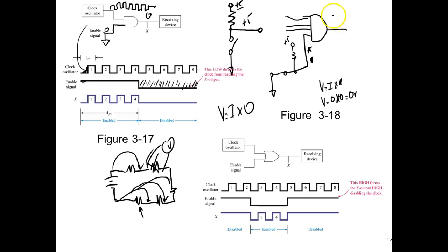It'd be a 0. That's exactly right. Well, what about those other inputs? They don't mean anything. I don't even care if they're highs. I don't even care if they're lows, right? You understand? As soon as you find a 0 on one input of an AND gate, then the output should be low, right? I don't care if it's got 100 inputs, which we won't see.